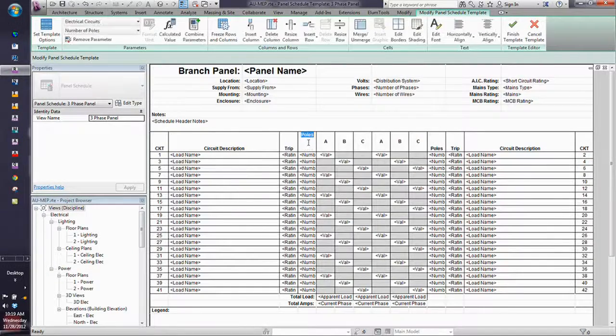So in this case, what we want to do is we want to add a wires table in here because this is going to make the schedule crunch down. That fixed width in there is what controls the size of the schedule. So anytime you insert a column, like we're going to put one left as selected in here, it's going to insert it on both sides. That's the beauty of the panel schedule in here.